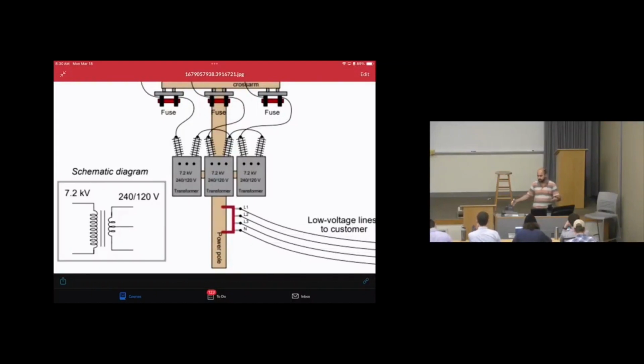For overall large scale, they will try to supply an equal amount of loads to the same system. So I would say for a specific neighborhood, let's say for phase A, we're going to connect 10 homes, phase B, 10 homes, phase C, 10 homes. Then the overall average of phase A will be the same as the overall average of phase B, the same as the overall average of phase C. So we are working based on average power that they can consume.